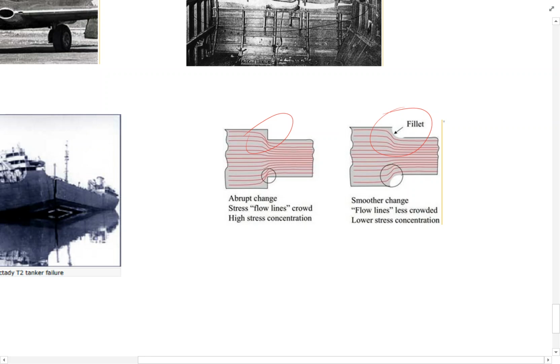So it's not something that I can fix with a higher yield strength material and have a huge impact. You can have a little bit of an impact, but you're probably going to lose ductility in doing that, so you're fighting yourself. The way to fix it is to change the geometric shape and put a fillet or a radius in there, so you get a nice smooth flow.